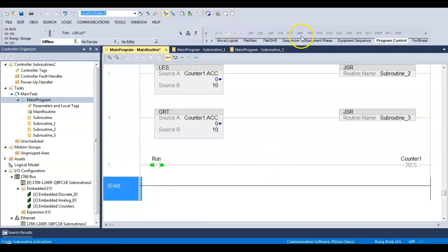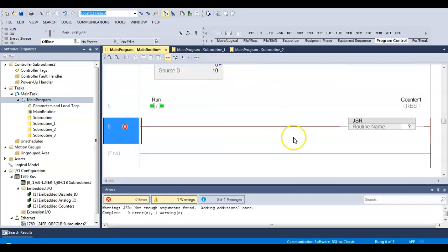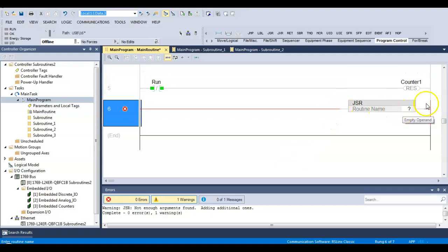And if you don't want to delete them, you can just come over here and double click, type in JSR, hit enter, and the subroutine that it puts in there doesn't have a lot. It don't have all those parameters. So you'll still have to give it a name. To give it a name though, you gotta create it first. So I kinda got backwards a while ago. So you need to create the subroutine before you give it a name here, right? Everybody okay? Subroutines are real neat.